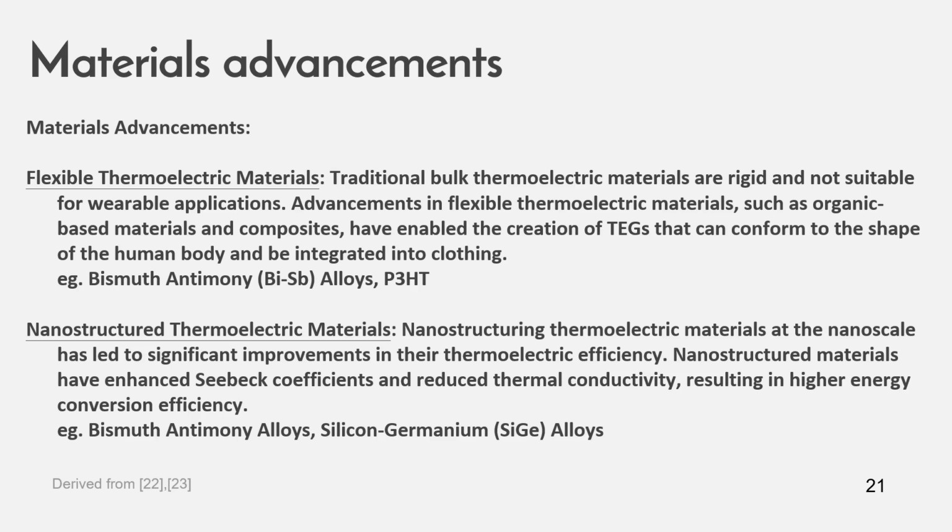And coming on to the second advancement, nanostructured thermoelectric materials. Nanostructuring thermoelectric materials at the nanoscale has led to significant improvement in their thermoelectric efficiency. Nanostructured materials have enhanced Seebeck coefficient and reduced thermal conductivity, resulting in higher energy conversion. So nanostructuring, the main purpose is to reduce the thermal conductivity of the material. And some of the examples of the materials which can be nanostructured are bismuth antimony alloys, silicon germanium alloys, etc.